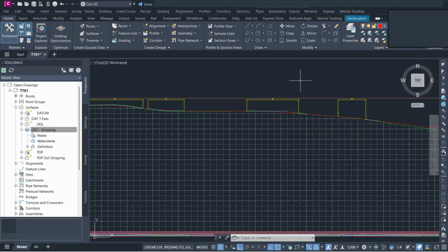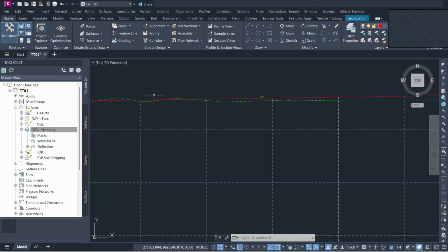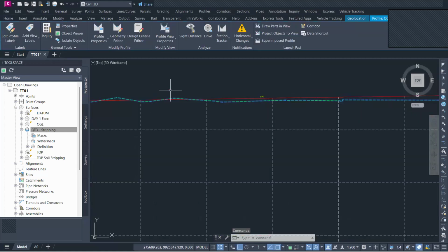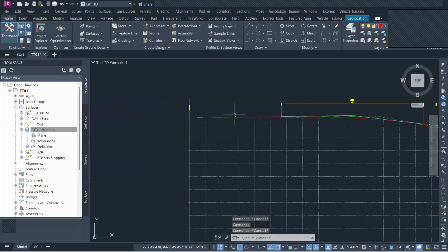I hope we are. Now, this red line that you are designing is not the finished road level. This is the formation level. It is very difficult to start by designing the finished road level. What we design is what we call the formation level.